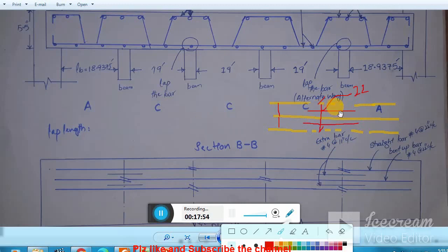So that's why you see here, now what will be the spacing? Clear? Now these are my top bars. So 22 is now divided into 3 parts, clear? 1, 2, 3, into 3 spacings. So this is 7 point something, okay, 7 point something. So this is the way you can adjust toward that 8 inch center to center. This is not actually 8 inch, but it is 7 point something, clear?